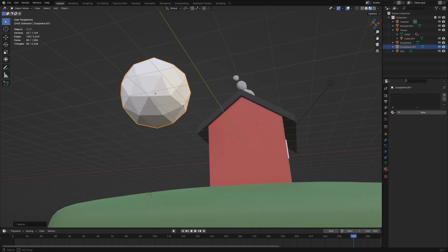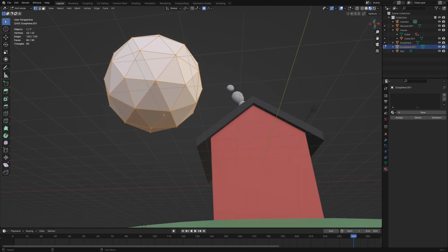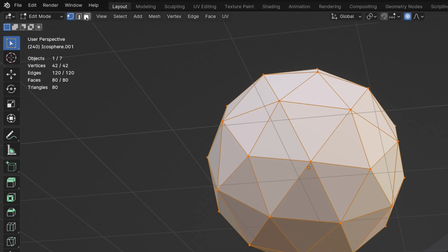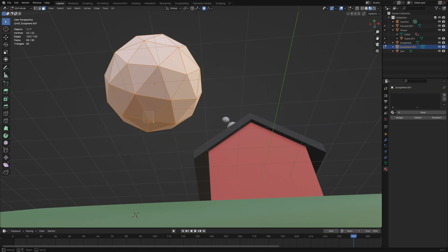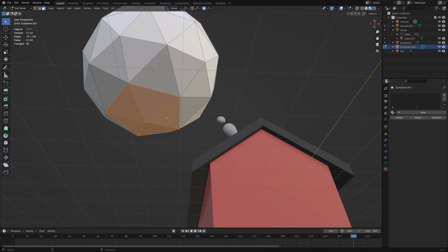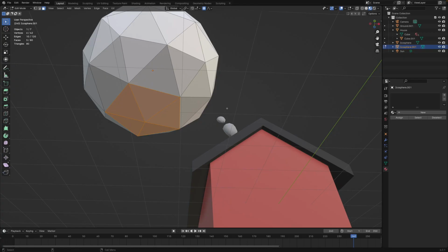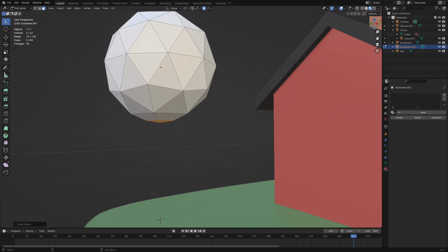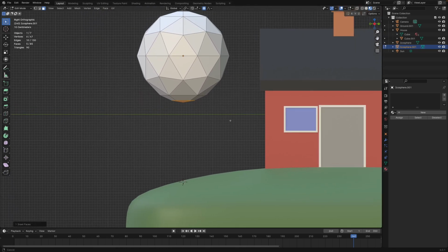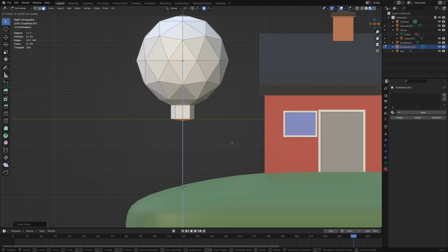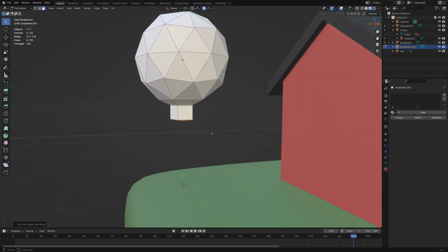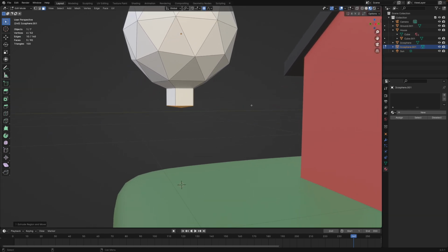And let's go into edit mode. Face select mode. I will select all of these faces. I will press I on the keyboard to inset. I think it's called inset. Yeah, inset faces. I, like that. Let's go to front view, clicking X, and then E to extrude. Yeah, that's good. E, extrude again, Z,